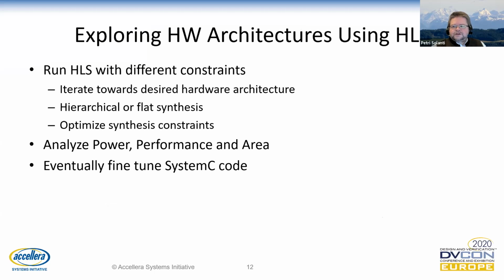When the design is quantized, we can explore the real hardware architectures. It is an iterative process trying different synthesis constraints, different module hierarchies, and sometimes also fine-tuning the SystemC code. Usually, the system architect knows what his desired architecture and performance are in terms of clock frequency and latency. This target is based on the experience from previous projects or static analysis with Excel. Sometimes some other architecture might be a better choice.